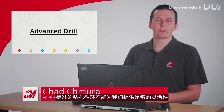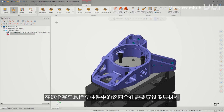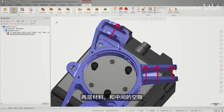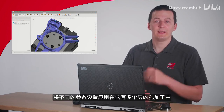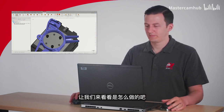Sometimes standard drill cycles don't give us enough flexibility for all the holes we need to create in a part. As you can see, these 4 holes in our Formula SAE Upright pass through multiple layers. There are 2 layers of material with a layer of open air in between. One of the key enhancements in Mastercam 2021 allows us to apply different parameters to each layer of material in multi-layered holes like these. Let's take a look.